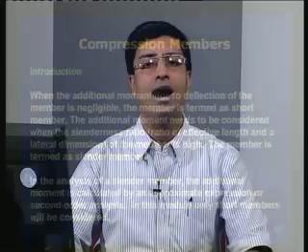Thus, if we have a slender member depending upon the slenderness ratio greater than a certain value, then we need to account for the additional moment generated due to the external compression, and this can be estimated by an approximate expression or by second order analysis. But in this lecture, we are considering only short members where the additional moment due to the deflection of the member is negligible.